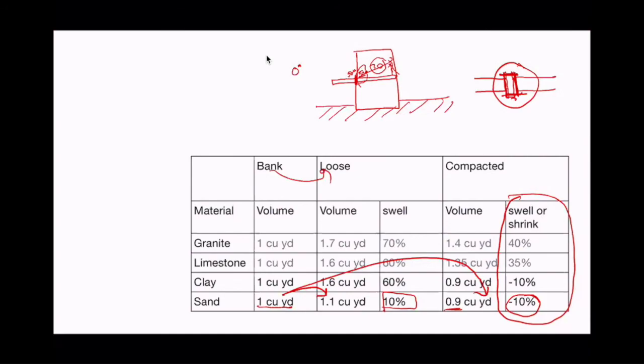So if, for instance, you had a door here in this building, and you have brick, that door may have a steel lintel. Say you have a wide flange, with your wall on top of the door and your door on the bottom. If you wanted to expose that wide flange on the inside and the outside because you like the way it looks, you can see how it's 0 degrees outside and 70 inside.